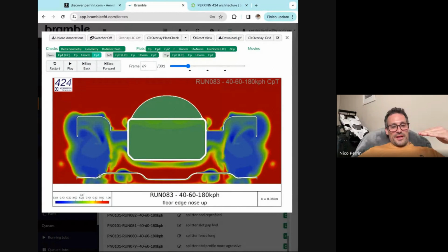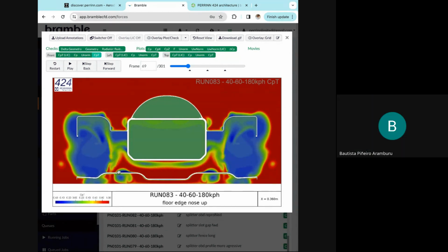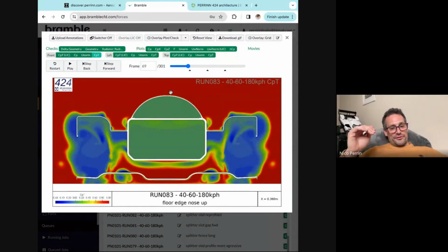But the floor starts and divides the flow that's not very high quality. You've got lower energy flow, and you're trying to keep only red under the car going under. In fact, that test didn't work because you're sucking some of the bad low energy flow under the car by opening that mouth. But in F1, the floor starts much later.